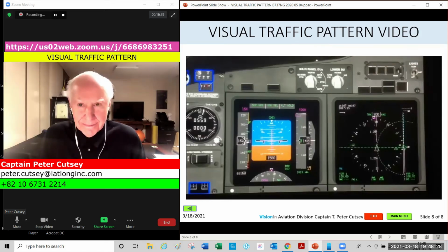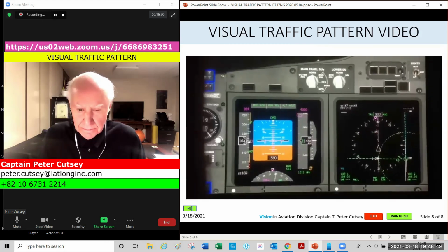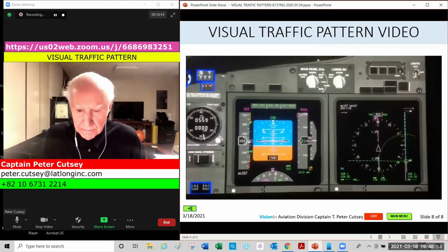We're looking at a 40-second timing. In the first 20 seconds, we will remain at flaps 5. At the 20-second mark, we'll select gear down, flaps 15. We'll set flaps 15 speed. For touch and go, no auto brakes and no speed brakes. Gear down, flaps 15, and flaps 15 speed.